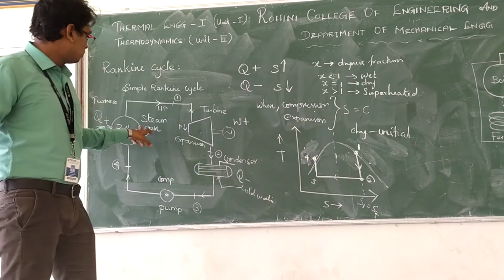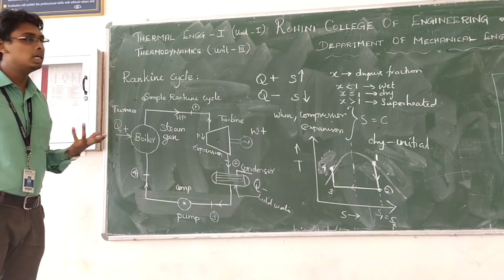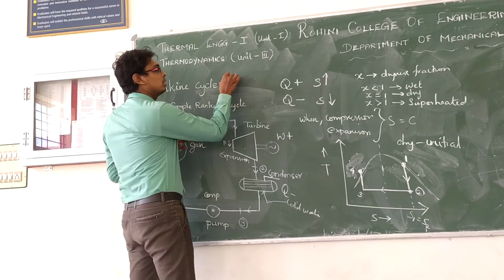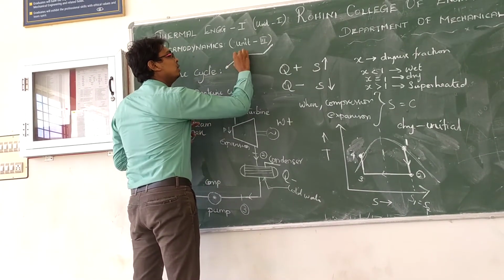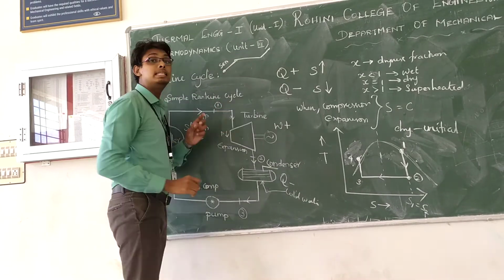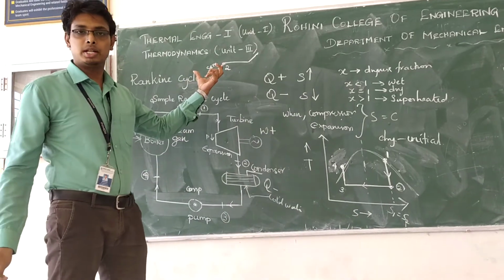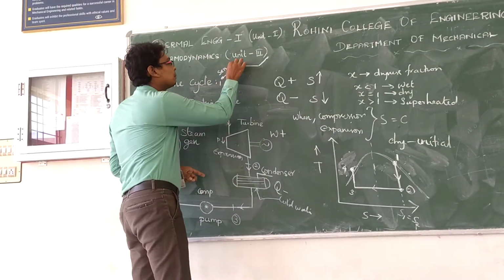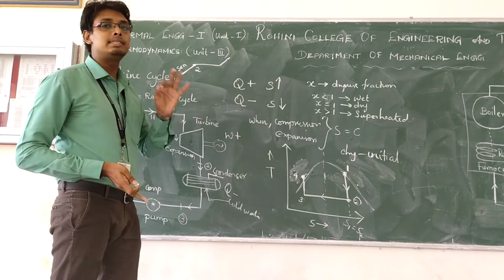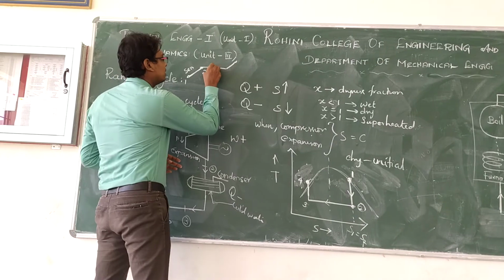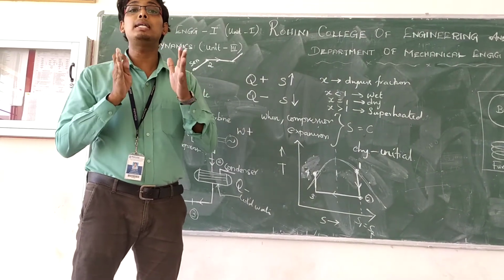Next again, the boiler. Boiler is a heat addition process. We are adding heat in the boiler. So always remember this. This is said to be sensible heating. This area is said to be sensible heating in the phase change diagram. The slanting, inclined curve always represents sensible heating, and the straight line along this graph is always a phase changing process.